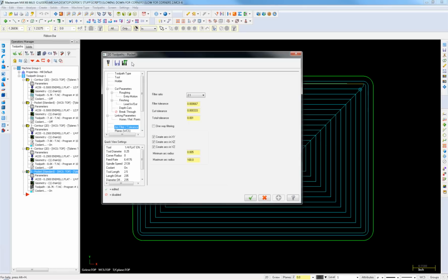Right. Out of curiosity, I hope a lot of people know the difference when they look at these things. I don't know if you covered that real quickly: when they look at the create arcs in XY, XZ, and YZ, actually what code changes to manipulate that to happen in the machine, the first one, XY, always being G17, the next one being G18, and then G19, the machine needs to see the change in plane along those planes. Right. What I usually do, which I think is personal preference, on my average everyday posts or defaults, I just leave the XZ and the YZ off.